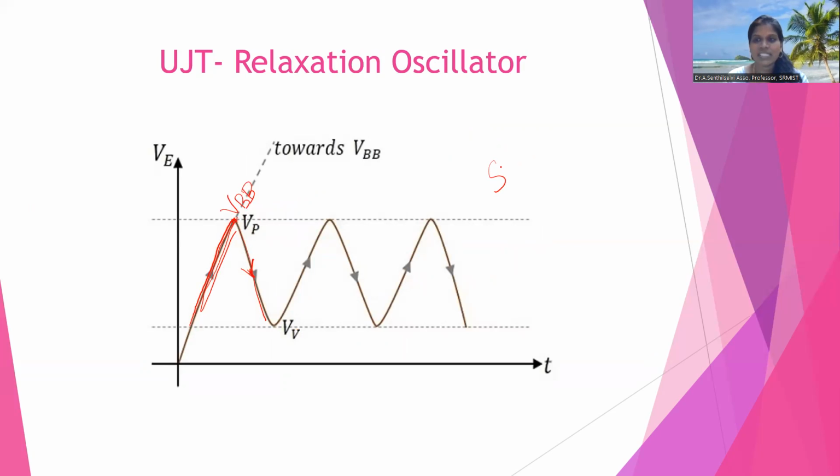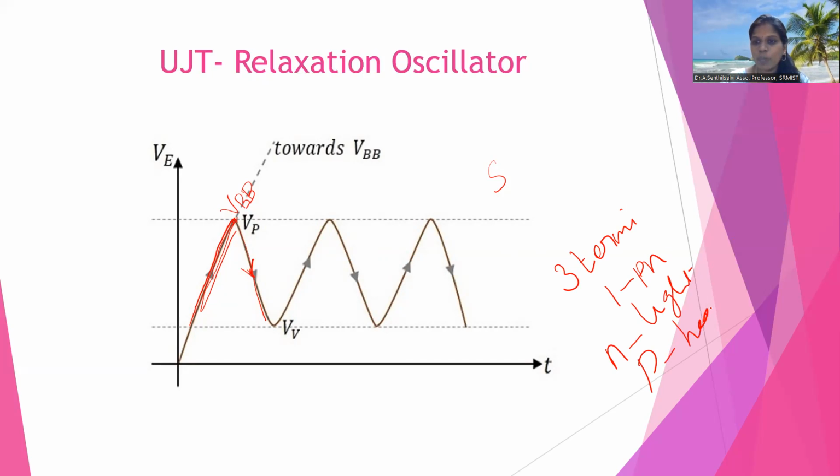As a summary of the class, UJT is a 3-terminal device. It has only one PN junction. The N-type bar is lightly doped and the P-type material is heavily doped. There is a high resistance between the two bases. For working, we divide into two cases: with the emitter connected to the ground, and with the emitter applied with some positive voltage.